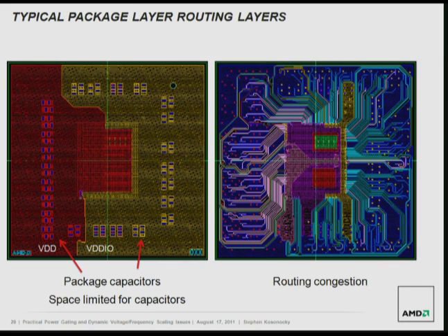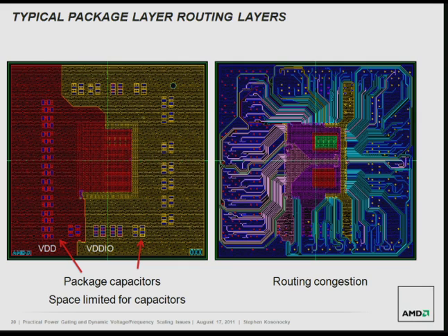If you look at how this really looks on die, on the left, you can see one of the planes showing the VDD distribution plane being shared with a VDD-IO plane. And you can see there are some limitations here in terms of how you effectively manage those power planes in a package. Because of that, it causes some limitations in terms of the voltage drop across the die.